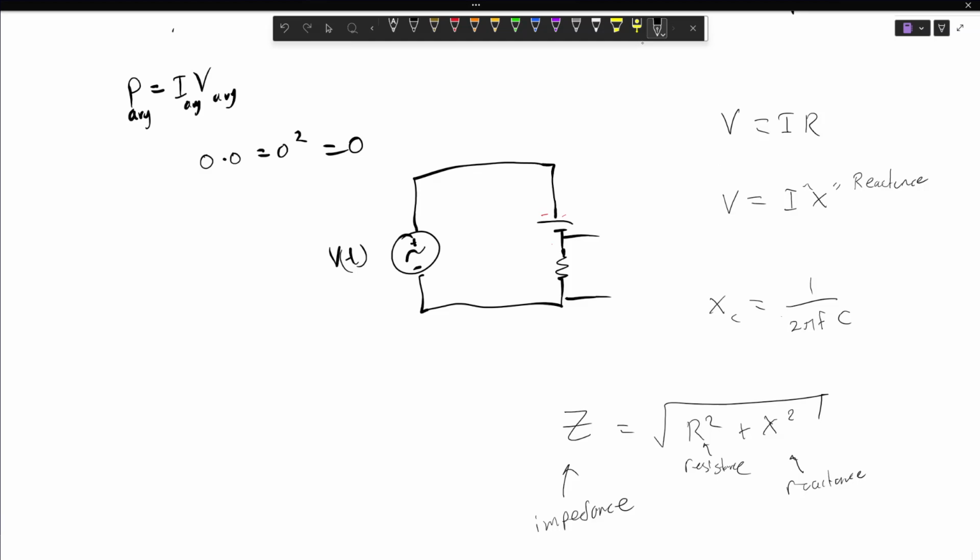So, for instance, a high pass filter is going to filter out all of the low frequencies that maybe we don't like. Maybe my voice is driving us crazy because it's this super deep low groan, and we want to make it a little bit more palatable. That's where we might put in a high pass filter to filter out some of those lower frequency pieces.